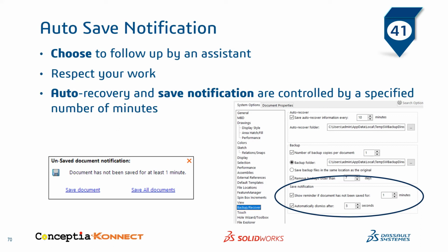Yes, go to System Options, Backup Recover, and change the reminder settings. Well, don't be in a shock for which I have chosen for every 1 minute. That's for me. And also select the auto dismiss time. Use it, thank me later.